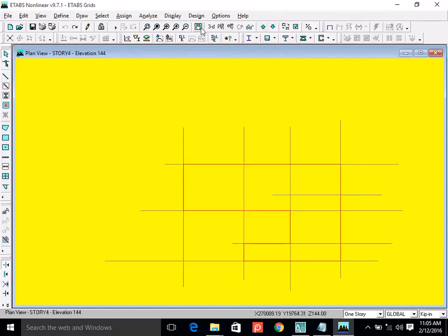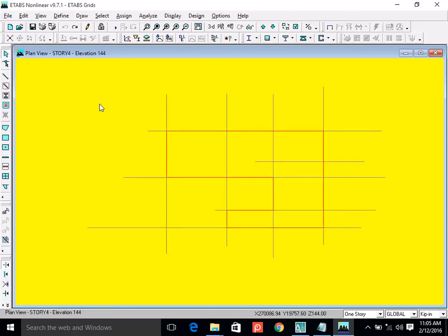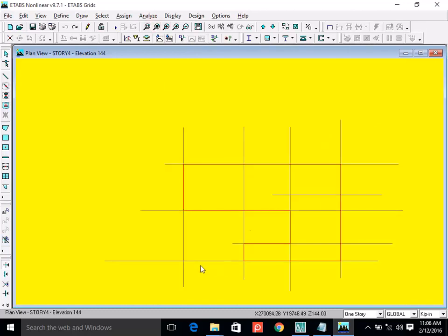Okay, one thing is very important, and that is about units. You have to be careful about the units. For example, right here, the distance which it is showing right now, look at the coordinates. The coordinates it is showing right now are in thousands of feet, 22,000 and 16,000. I don't know what is the understanding of the software. For example, the origin is right there in the corner, in the software, the global axis.